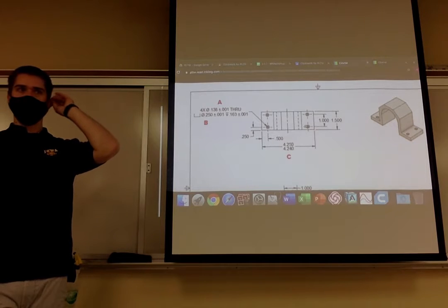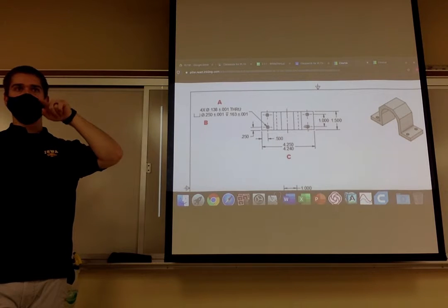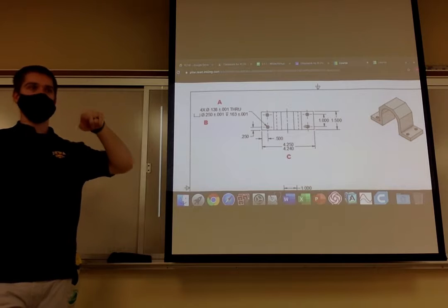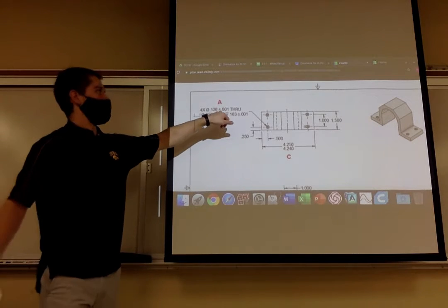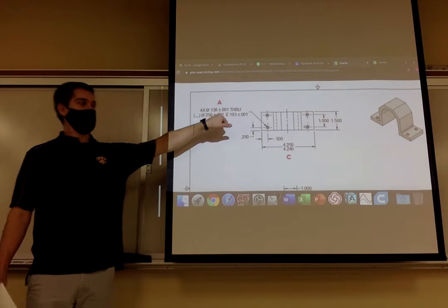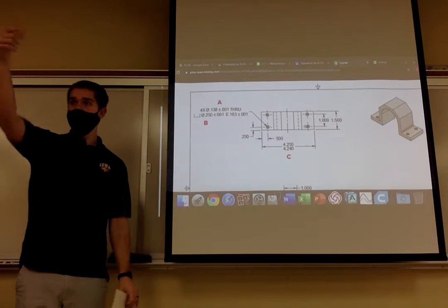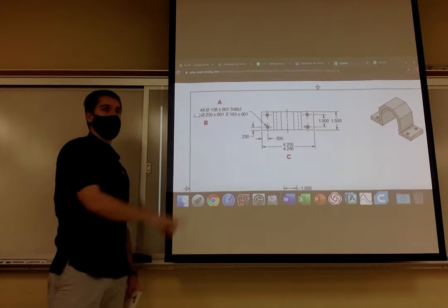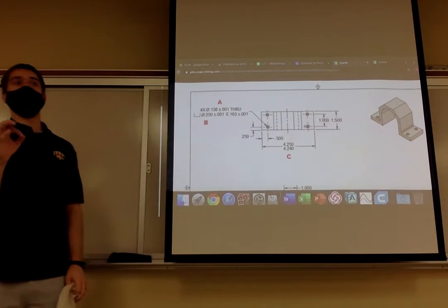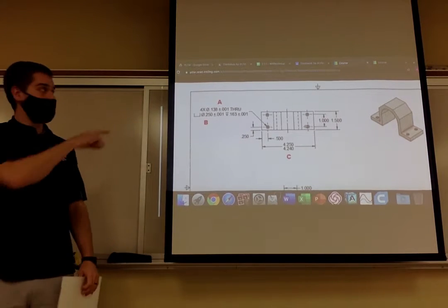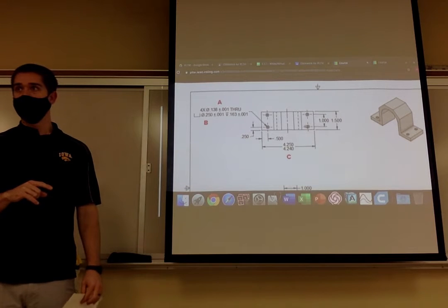I need you guys to be with me here. Adrian? Yes. Good try. They were saying bilateral because you're seeing a plus and minus. I'm giving you room for error above or below my specified dimension. Now, what's the total tolerance that you're allowed on this part? 0.002.